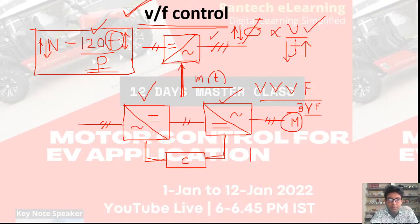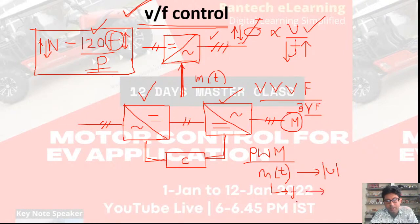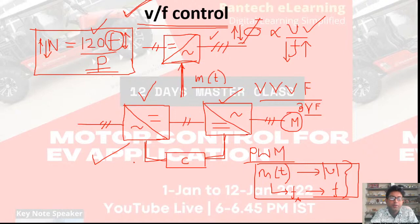Once the concept of PWM evolved, then by changing the modulation index of the modulating signal, I am able to control the amplitude, and by changing the frequency of the modulating signal, I am able to change the power frequency. This is done by one inverter alone. Okay. So this is the very basic of open loop V by F control.